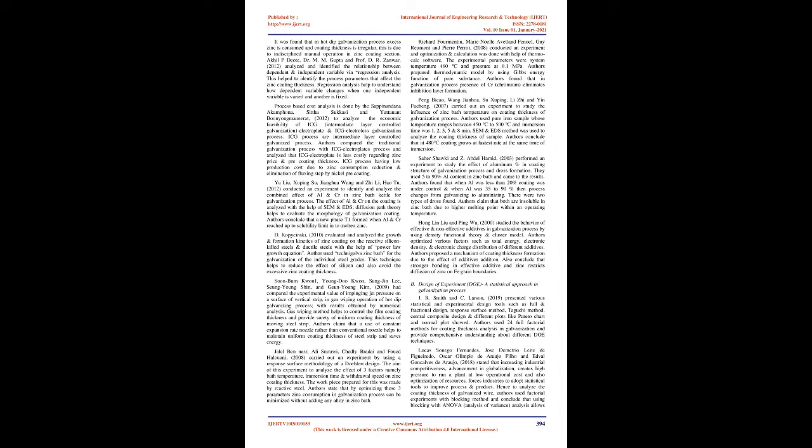Mr. Sanjeev Kumar and Satyendra Kumar Chaurasia, 2015, proposed the idea of Mg, magnesium, addition into the zinc bath for galvanization to improve corrosion resistance of the conventional hot dip galvanization process. Authors performed a coating simulation experiment on commercial quality cold rolled sheets. The galvanization process parameters are Mg level, 0.25 to 0.75%, bath temperature, 420 to 460, and dipping time, 2.0 to 4.0 seconds.